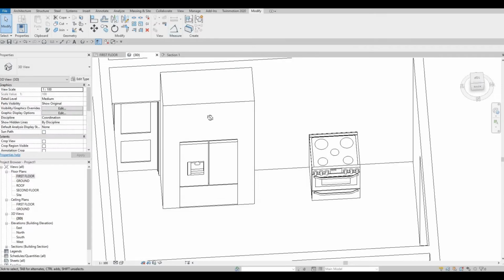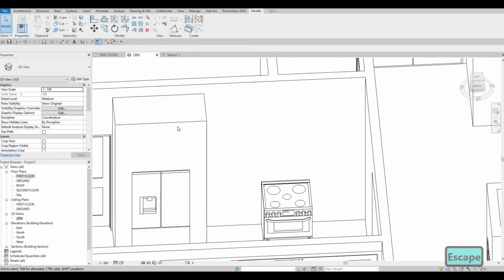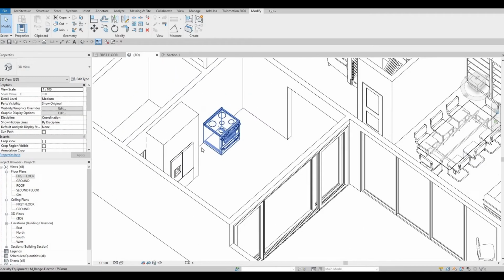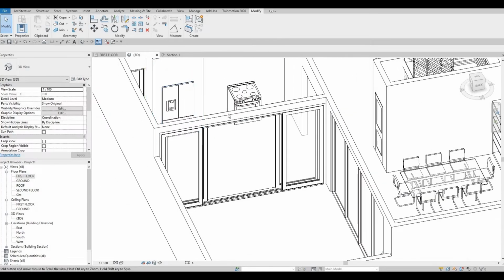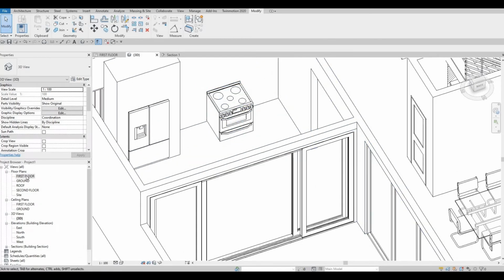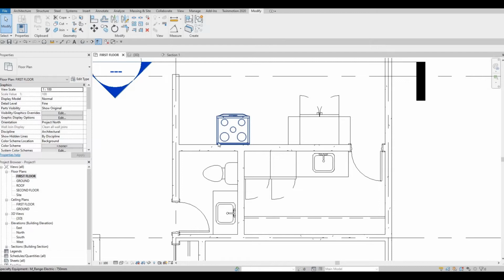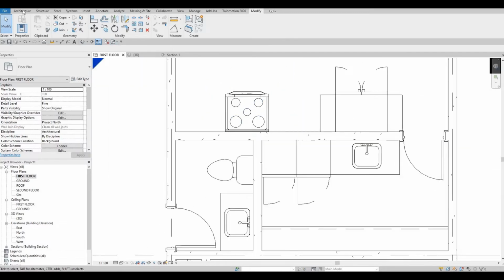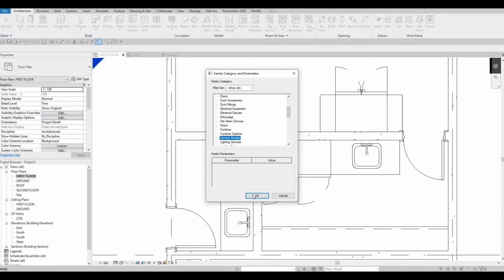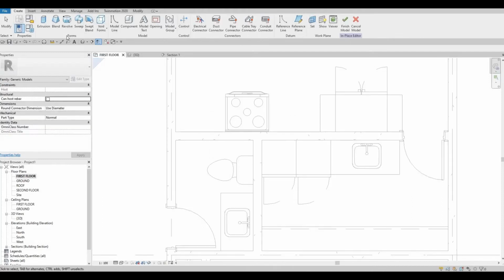Now you could click on finish. I'm good with that. And then now we need to just create a linear. So it's going to be easy. We could just have from the top. So go to first floor. And then from here, we're going to create. So click on architecture, model in place, generic model. And then here, extrusion,